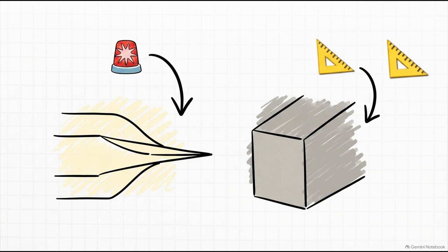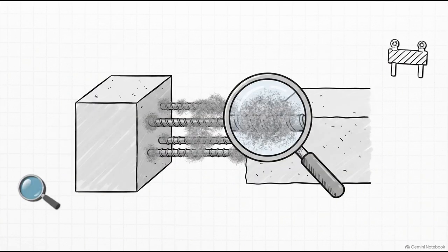If a specific angle is required for the joint, it needs to be cut and roughened while the shotcrete is still plastic, way before it becomes too hard to shape. Let's switch into inspector view for a second. When you're looking at a joint, don't just stare at the concrete face. Zoom in on the steel crossing that joint.